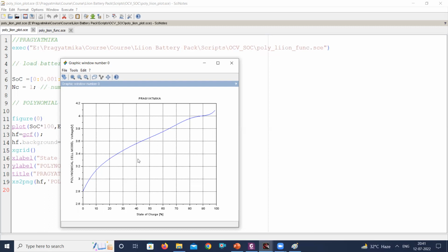The thing is that SOC is for our reference only. SOC does not have any relevance as a real physical quantity of the cell. The real physical quantities of your cell are voltage and current, and using these two we can have the capacity and energy. As the capacity is fading, meaning depleting, it does not mean that life is fading. It means that the cell is getting used, and the capacity is getting utilized for the application to run. That is leading to the depletion of the SOC value. And once the capacity is fading, specifically in the NMC cell, our open circuit voltage is also dropping down. That's the relation we are deriving here.